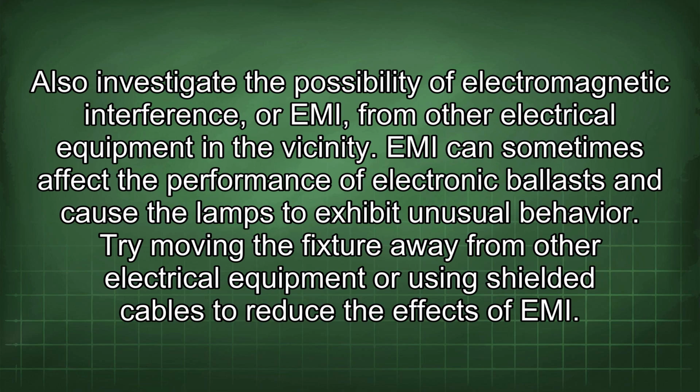Also, investigate the possibility of electromagnetic interference, or EMI, from other electrical equipment in the vicinity. EMI can sometimes affect the performance of electronic ballasts and cause the lamps to exhibit unusual behavior.